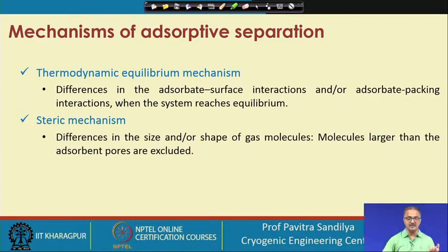Then we have another mechanism, that is the steric mechanism. In this, differences in the size and/or shape of gas molecules dictate the separation. That means the molecules which are larger than the pore size will not be allowed through the adsorbent, whereas those molecules which are smaller than the pore size will be allowed to enter the adsorbent particles and then get adsorbed. So this is called the steric mechanism.